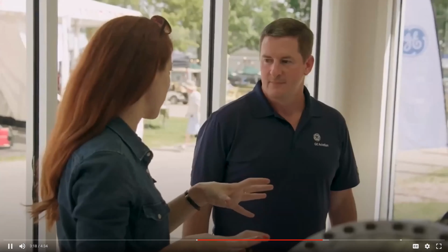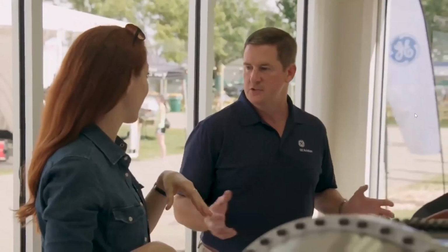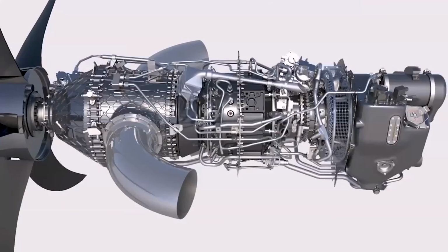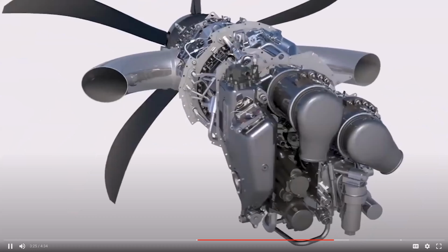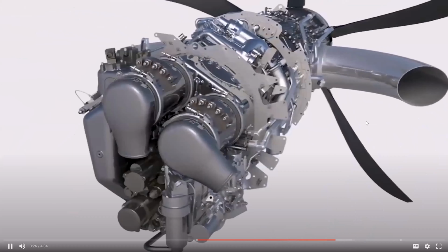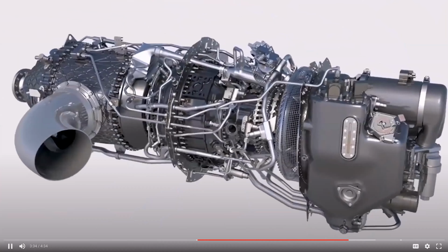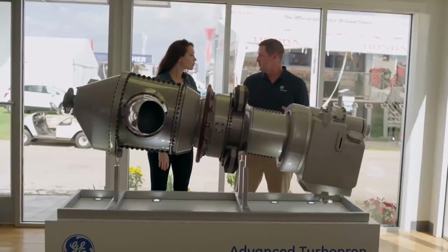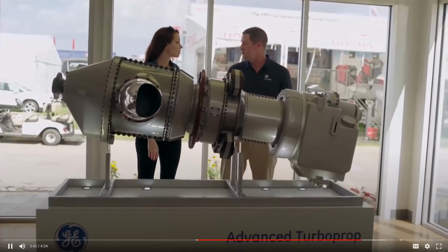It's really the world's first engine with extensive use of additive. Basically, we took 855 parts that would normally exist if we did it conventionally, and condensed that down to just 12 parts. Those are large, complex assemblies that people have to assemble together, and those parts add weight, they wear out, and they create leakage paths, which robs the performance and efficiency of the engine. So the end result is a combination of technologies that we've really never used on small engines before. What do these parts look like?